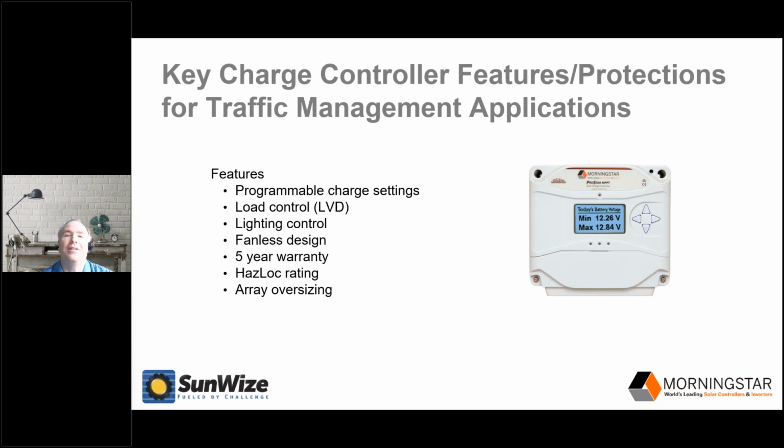And in terms of heat dissipation, it's advantageous for a controller to have a fanless cooling design to dissipate heat. Conversely, controllers with fans suck in dust and debris over circuit boards, which compromise performance. Fans can also be noisy, they're a parasitic load, and they represent another point of failure. So all Morningstar controllers are fanless with passive cooling.